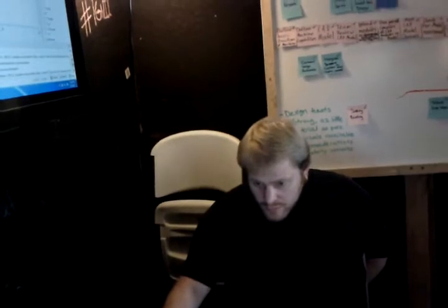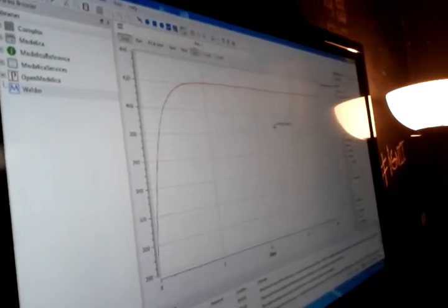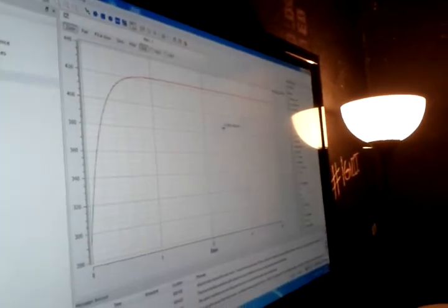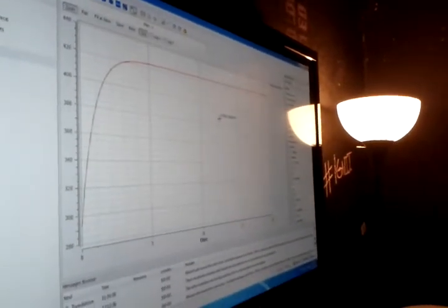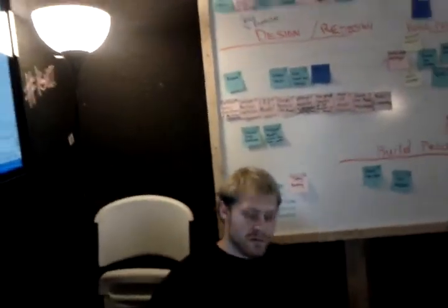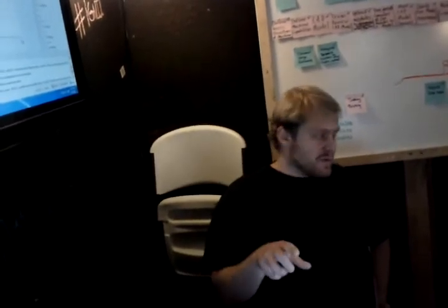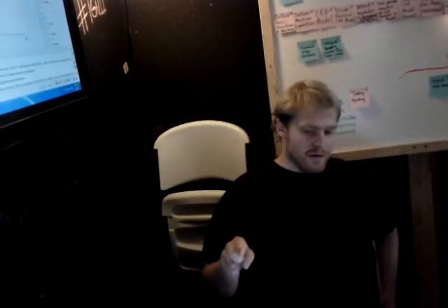So if we go back in here, we can open that up and follow its heat port and its temperature profile. So we can determine what its steady state temperature is going to be and if that's too high or not. And then we can change other components in order to bring it down. So being able to create that model and then just vary those components in order to get the operation that you want is advantageous. This is something that can be used immediately.